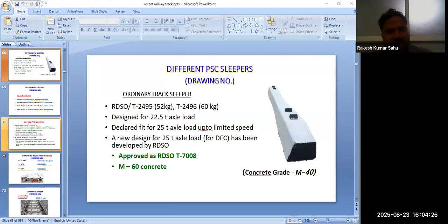Also, heavier sleeper provides more longitudinal and lateral resistance to counter higher thermal force on account of rail. Also, longitudinal forces like traction and braking exerted by heavier trains, it can bear. So basically, wider sleeper gives a safer structure as compared to normal sleeper.